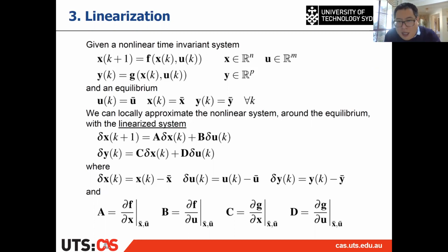But in the nonlinear case, we can also do some transformation, not from continuous to discrete, but from nonlinear to linear, which we call linearization. In the linearization, we can linearize the nonlinear system to get an approximated linear discrete time system.